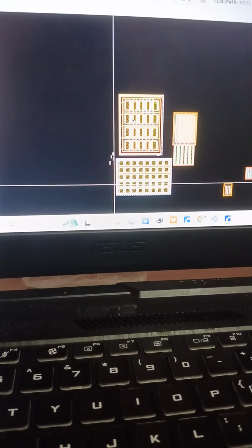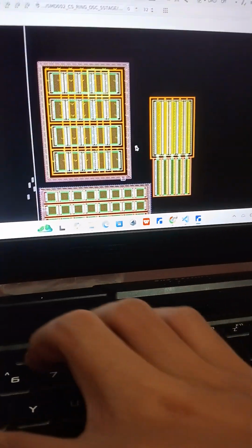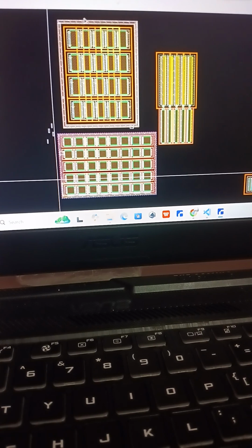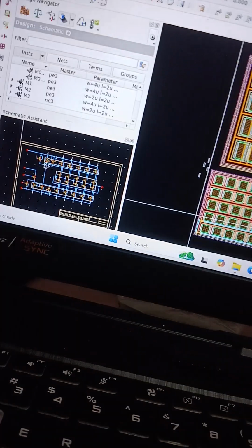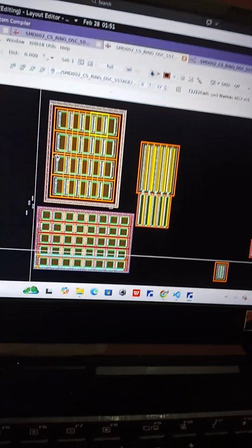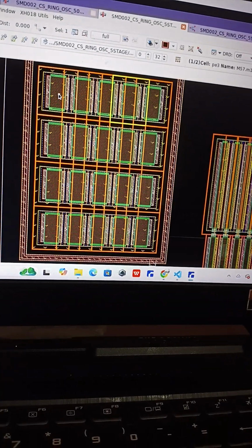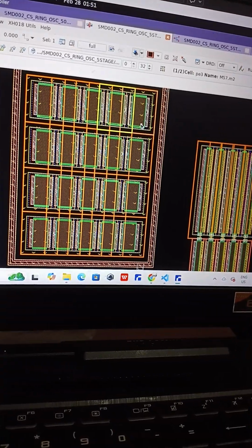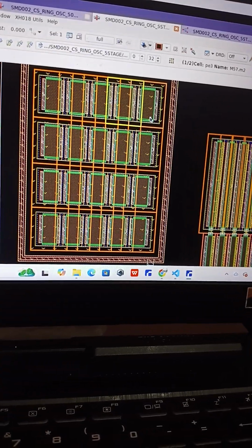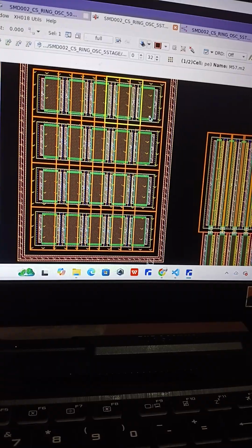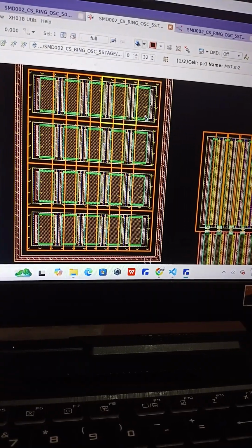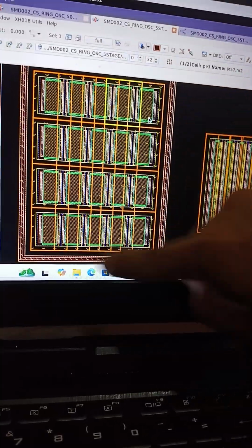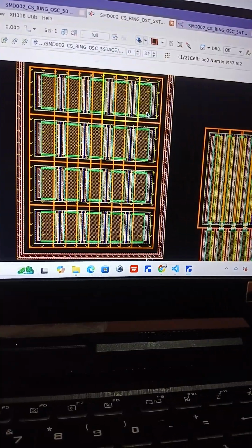So that's why the first thing we need to consider is basically, before you do any kind of connections, you need to check the placement. The placement of the transistor is very important in layout design. What I mean is in layout design, we need to consider the matching properties, right? So we want to make sure that all of the devices follow the matching rule.